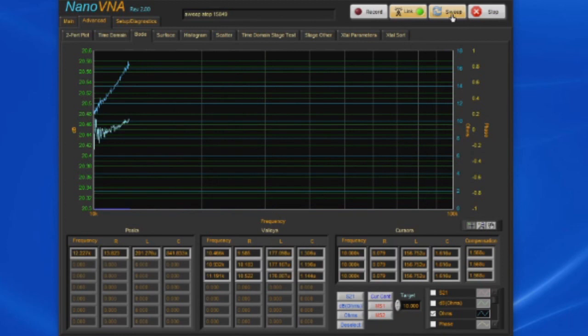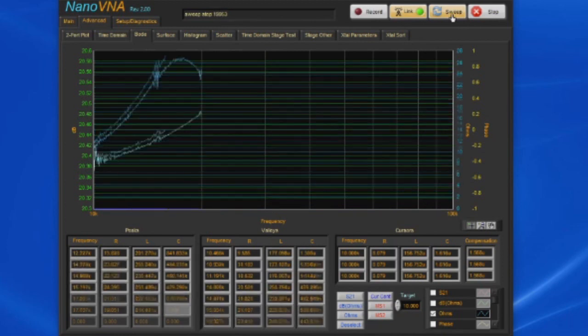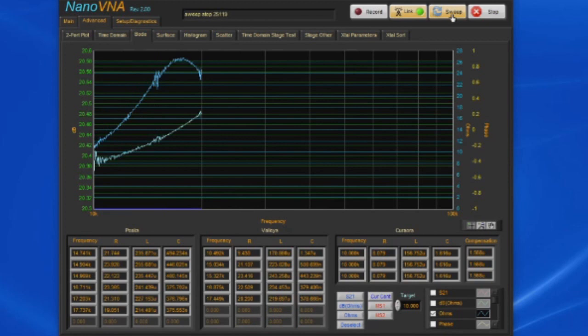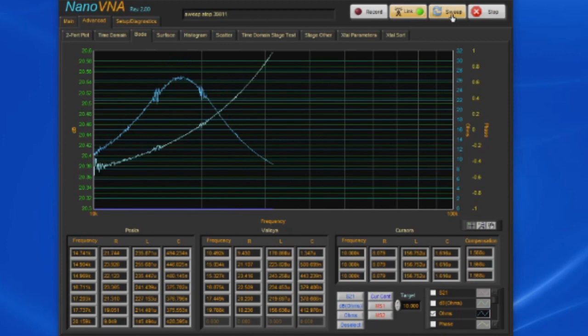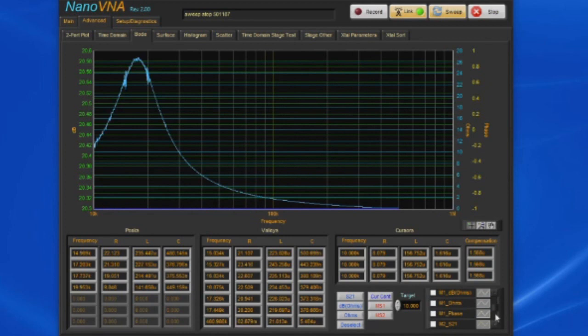We expect that this should have a much flatter impedance, and it better be closer to 10 ohms. So let's see. Oh, it shot all the way up to about 26 ohms, and now it's coming back down. There's 5 ohms. Let me just turn off memory 1, which will allow us to zoom in a little easier. Okay, it doesn't look very flat. It's gone all the way from 10 ohms basically up to about 28 ohms, and then down to essentially 0 ohms. So what's the problem?